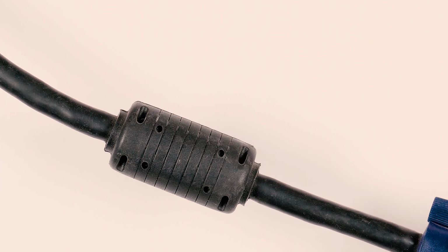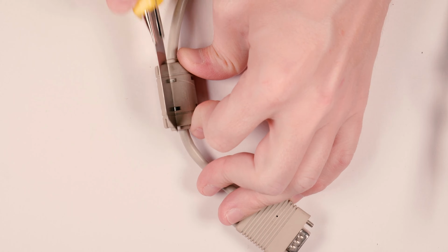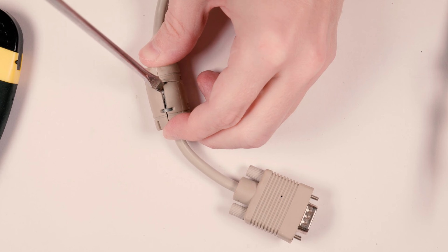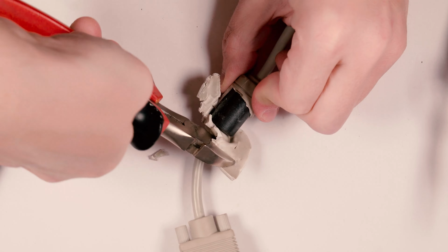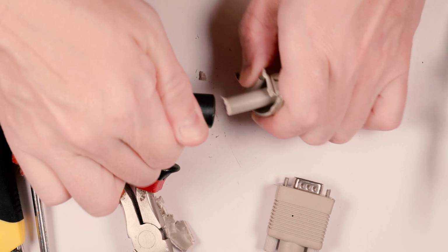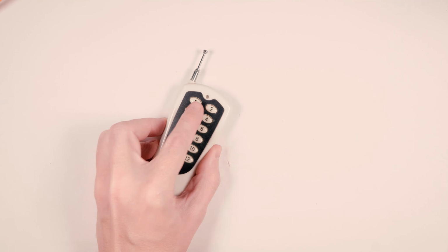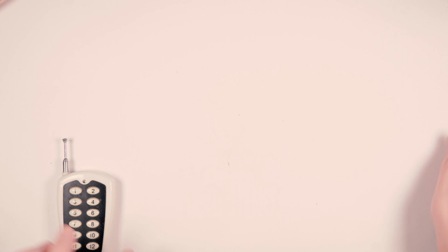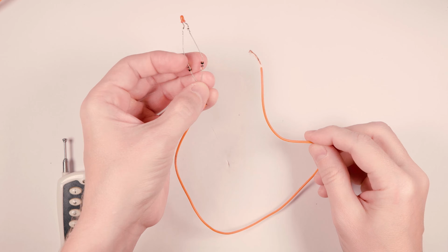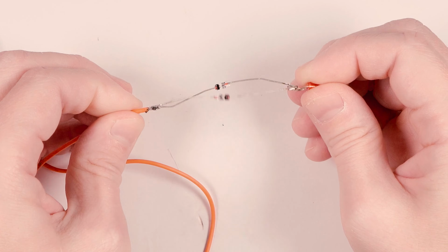Let's stage an interesting experiment. I'll take an old Super VGA cable, fortunately there's an abundance of this stuff now and everyone throws it away, and extract the ferrite cylinder from it. Then we will need a radio transmitter. You can use any radio remote control operating in the range from 200 MHz and above, as well as a simple detector using two germanium diodes with an LED and a wire soldered to them.